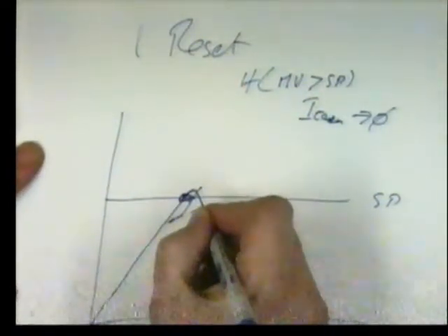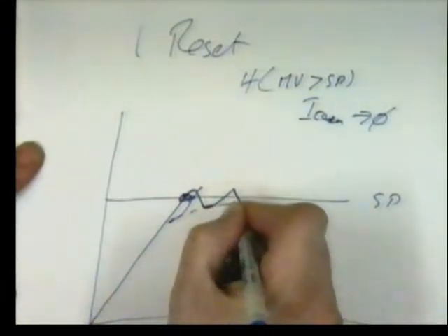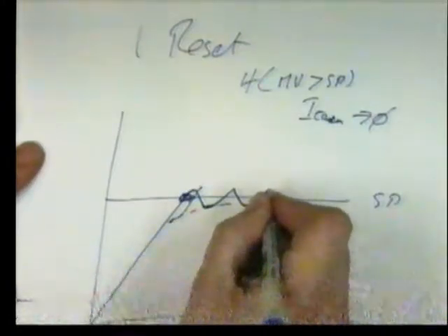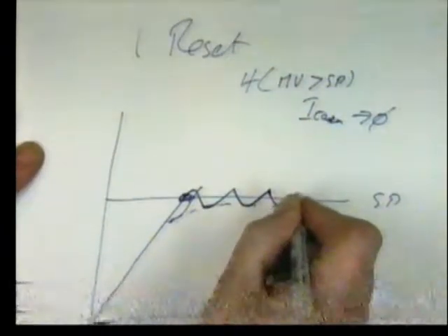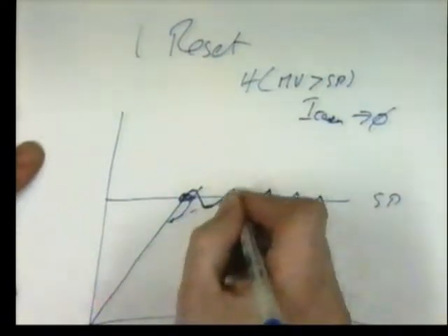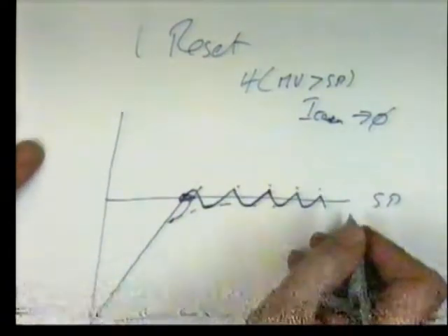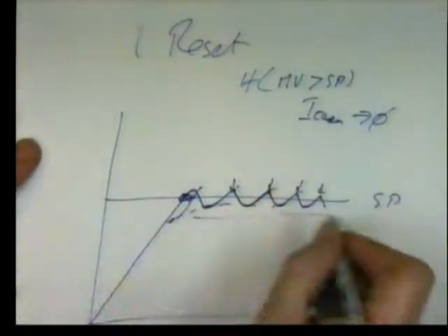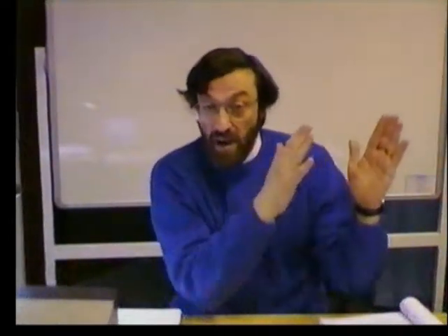And what you tend to get is an effect such as this. Nice smooth control up, PI, there's the I term, switched off, and it drops down. Very jerky response at that point, very high frequency components in these signals, but it does do the job. It stops it running away. So there we have 3 computational techniques: using a running mean, the array of only the most recent data, not all the data, an integral clamp, and an integral reset.